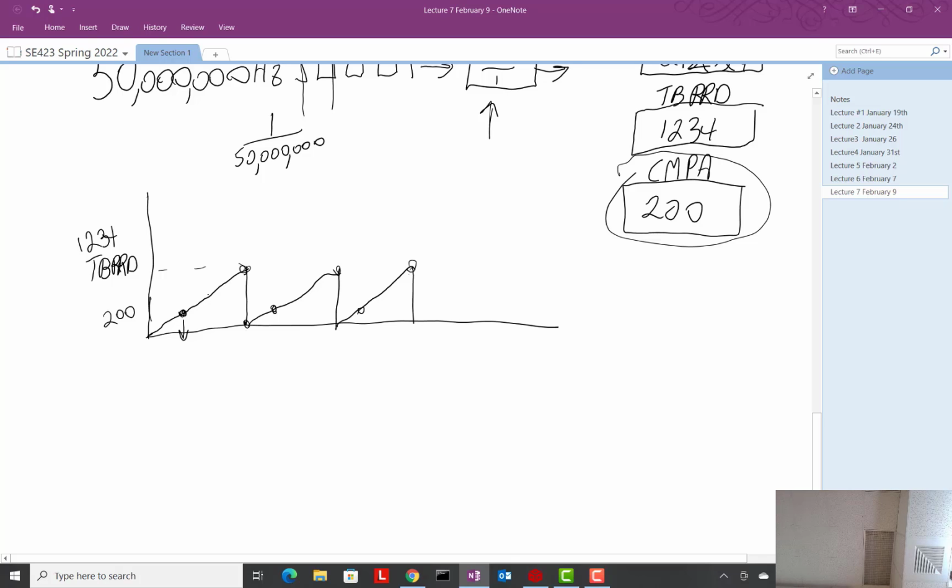And what we're asking you to do in this exercise is to, whenever the counter equals 0, in other words, when it's reset to 0, we want to pull our IO pin high. So think about what that would do. Our IO pin, well, it's 0 here, so boom, it gets pulled high. And then when TB counter equals 200, it goes low.